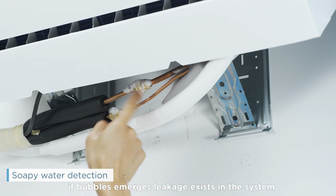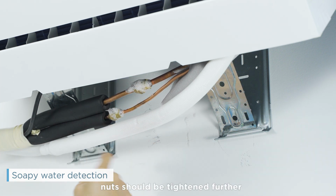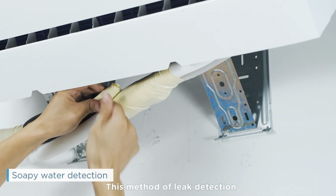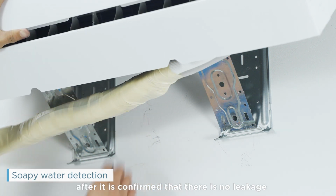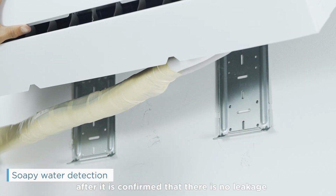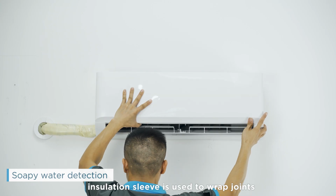If bubbles emerge, leakage exists in the system, and the nut should be tightened further. This method of leak detection is equally applicable for the indoor unit. After it is confirmed that there is no leakage, an insulation sleeve is used to wrap the joints.